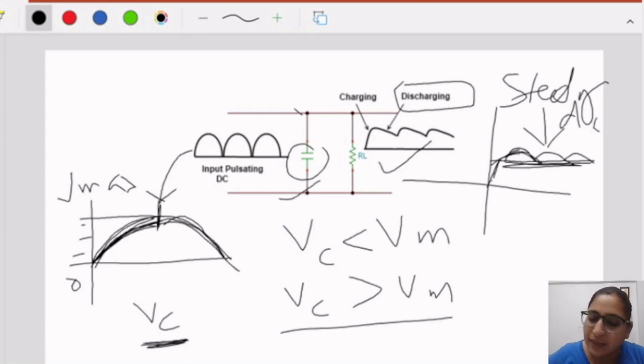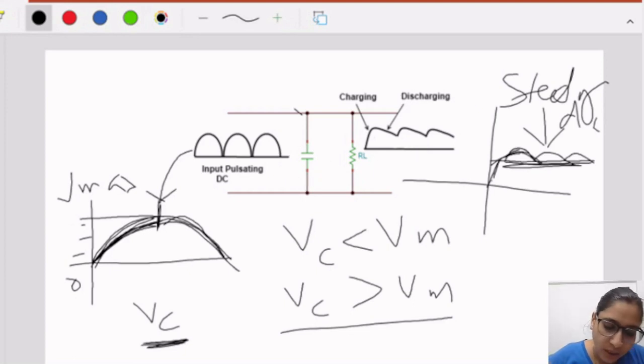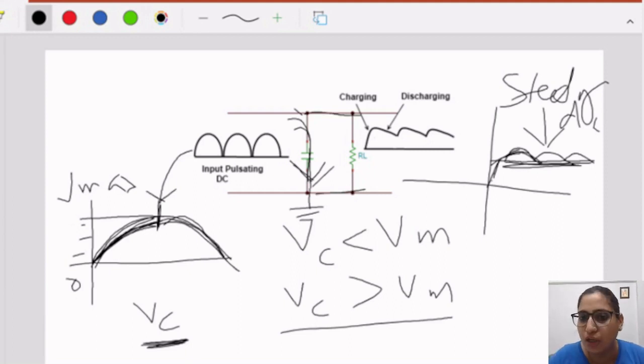Now, we are connecting this capacitor in parallel form. What is the need for connecting it in parallel form? When the AC component is coming, it will pass through the capacitor, and at that time this capacitor behaves like a shunt or short circuit. So all the AC components coming are grounded, and at the short-circuited output we will get only the DC component.